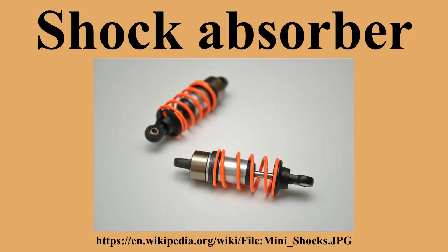Dry friction is used in wheel brakes, by using discs at the pivot of a lever, with friction forced by springs. Used in early automobiles such as the Ford Model T, up through some British cars of the 1940s, although now considered obsolete. An advantage of this system is its mechanical simplicity. The degree of damping can be easily adjusted by tightening or loosening the screw clamping the discs, and it can be easily rebuilt with simple hand tools. A disadvantage is that the damping force tends not to increase with the speed of the vertical motion.